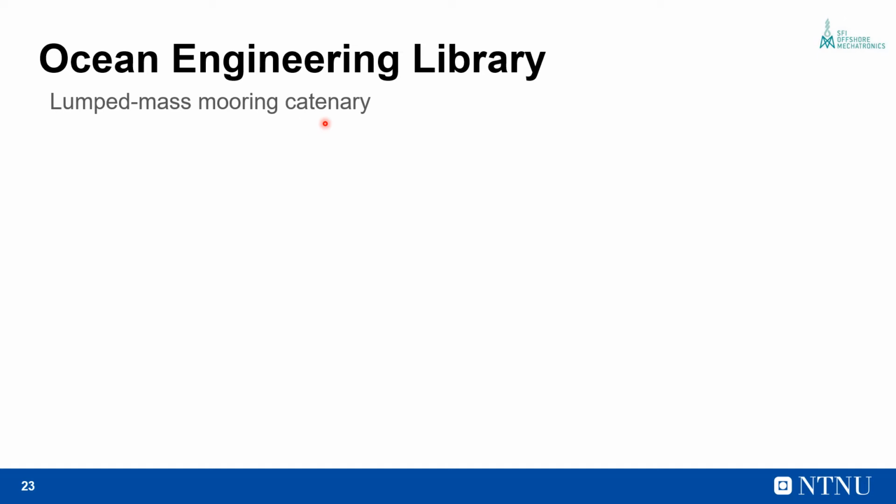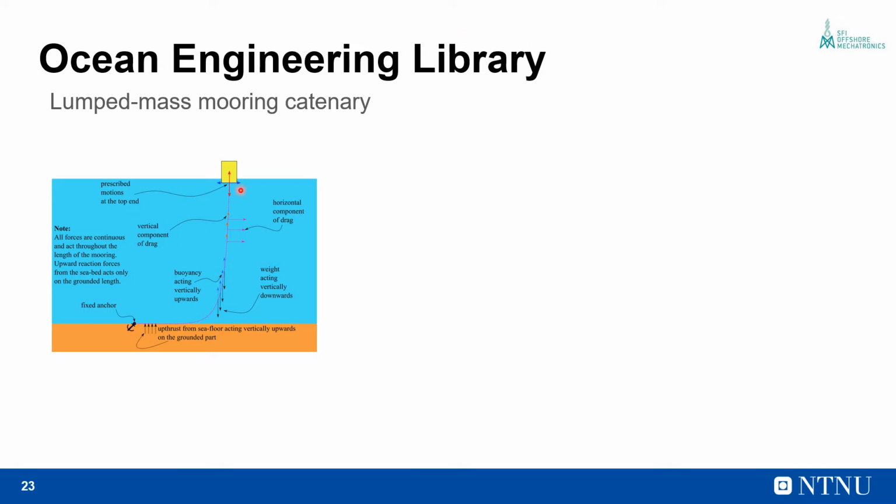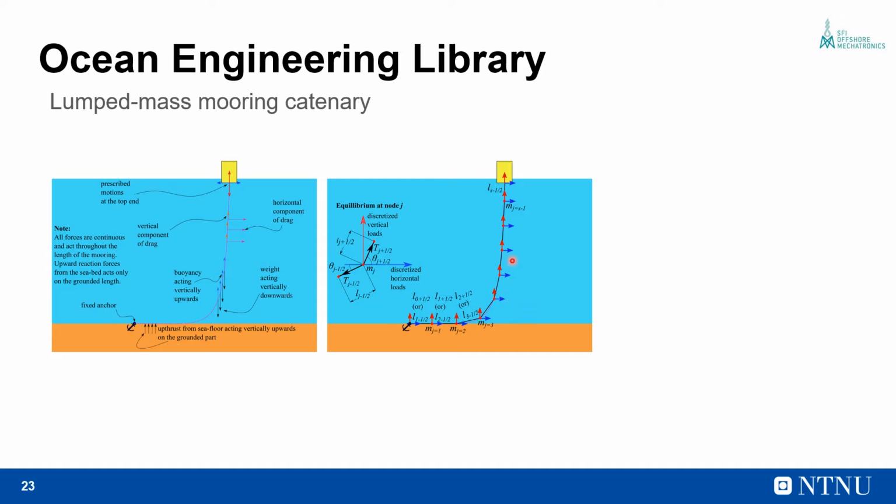We talked about the limitations of the quasi-static catenary theory in that it cannot capture effects of the dynamics of the mooring line itself, and that it does not account for the deflection of the mooring line caused due to the fluid loads. Hence, we decided to implement the lumped mass approach in calculating mooring forces. In the lumped mass approach, the continuous loads acting on the mooring line are discretized and applied at nodal points.